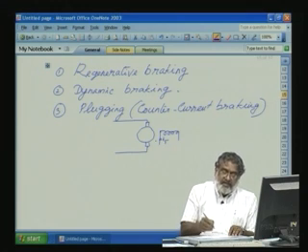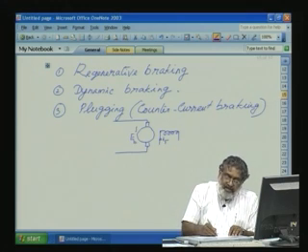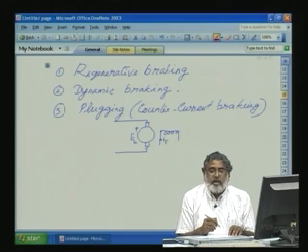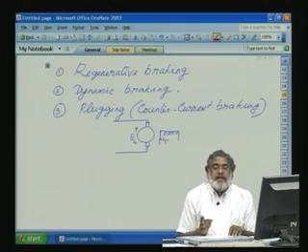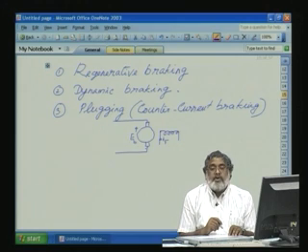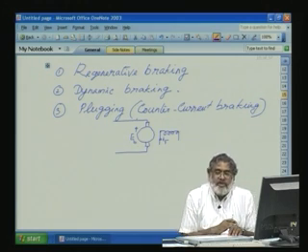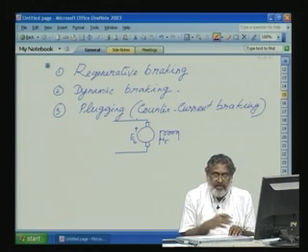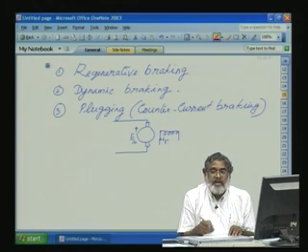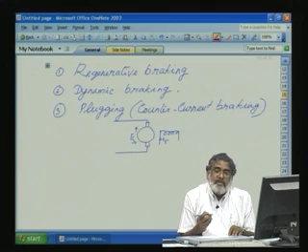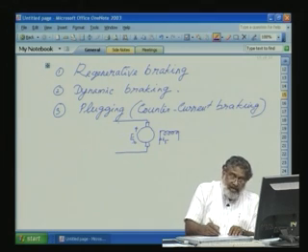There is a back EMF here, EB. The machine is still running because the inertia of the system is so high, we will not be able to quickly change the speed, but we can change the current direction quickly. That depends on the electrical time constant. Back EMF depends on the rotation and it depends on the mechanical time constant. So, the mechanical time constant will usually be large.